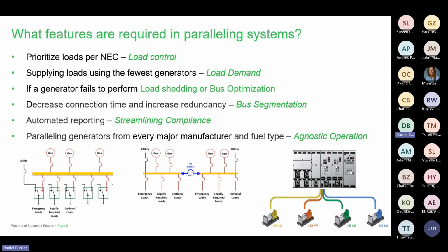Just a side note that I always like to point out to the consulting engineering community, we need to be sure that the pitch, if you do not understand what that is, reach out to us. But if the way the generator is wound is a 2/3 pitch, each additional generator needs to be of the same pitch. Just to digress on that for a minute, why?